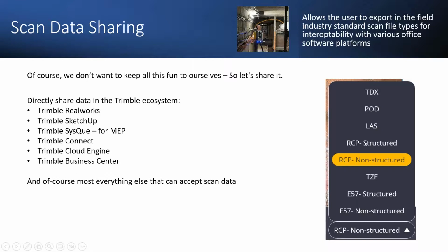You'll see here that there's 2 different types of data, structured and unstructured or non-structured. What structured is, it actually keeps the scan station locations as part of that data set. Non-structured is, it's just going to lump it together and say I have one giant point cloud of registered point cloud data. Most people typically go with the structured, so you maintain that station setup.